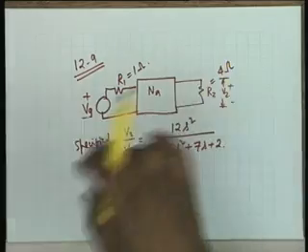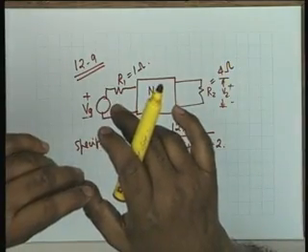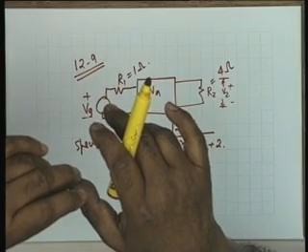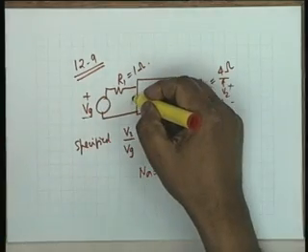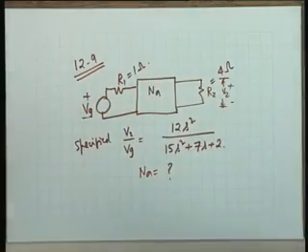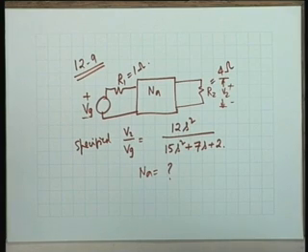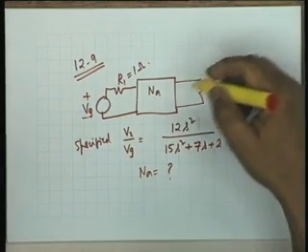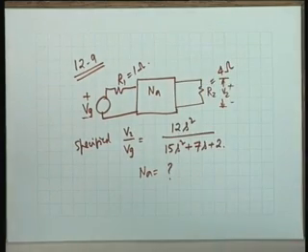Those nice procedures, Z21, you divide by the odd part or even part, that doesn't hold, because you have a termination on both sides. So we can find the input resistance here. How does that help? Then we can convert the voltage source into a current source, take the 1 ohm and add it with the 4 ohm over there and make it 5 ohms.